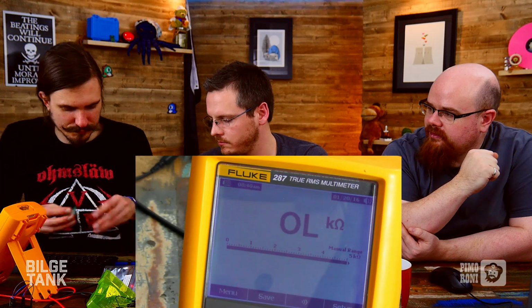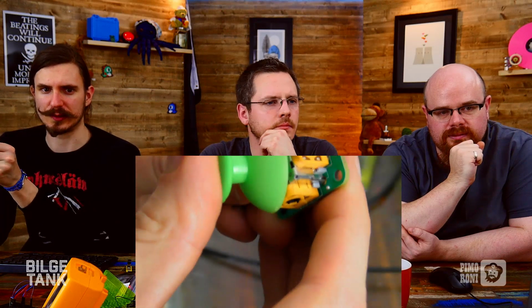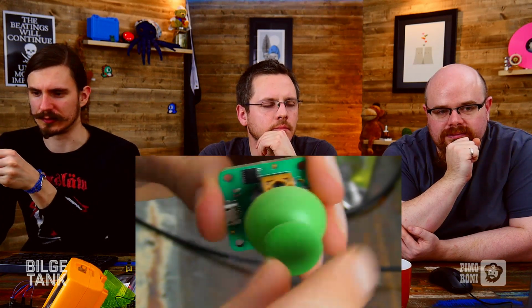Most modern sensors now have the ADC integrated, so light sensors will have a built-in ADC and an I2C interface implementation inside, but they're almost always surface mount only. So for hobbyists, it's much easier to hook up something like this. But that leads on to the Flotilla things you've got there. It does indeed. These are actually not ADCs, but PIC microcontrollers that we have told to do nothing but pretend to be an I2C ADC that reads the channels we want it to. So for the joystick, we're reading an X and a Y channel as analog inputs, and a button press as well.